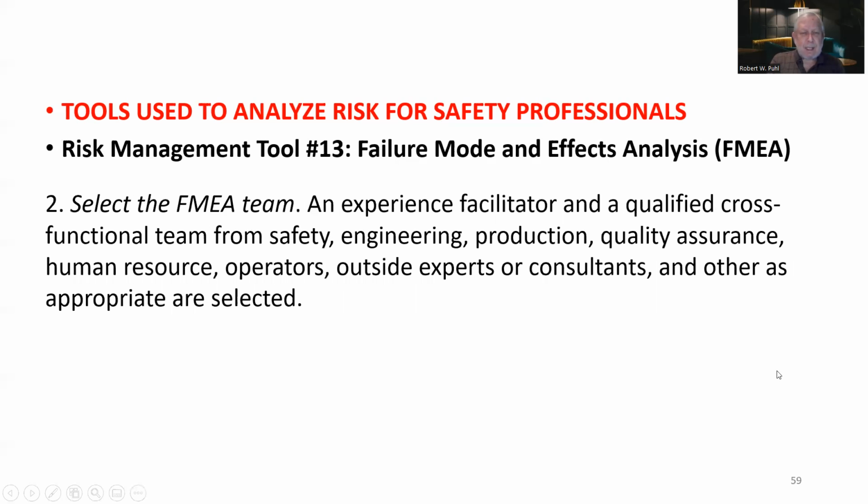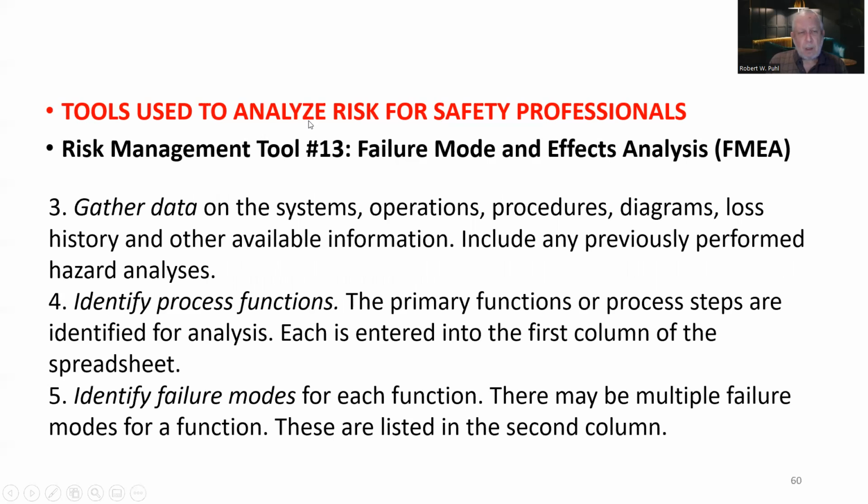Select an FMEA team, an experienced facilitator, and a qualified cross-functional team from safety, engineering, production, quality assurance, human resources, operators, outside experts or consultants, and others, as appropriate. This team can be pretty good size sometimes. Gather data on the systems, operations, procedures, diagrams, loss history, and other available information, including any previously performed hazard analysis. And get all your stuff together.